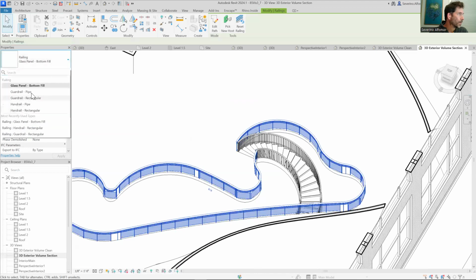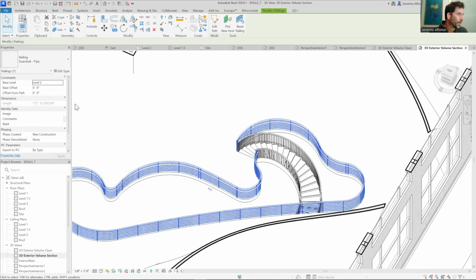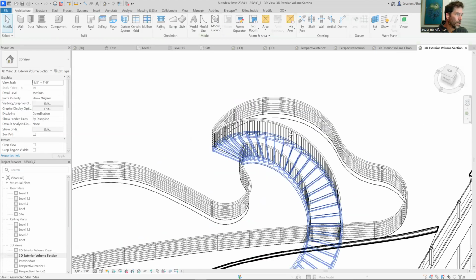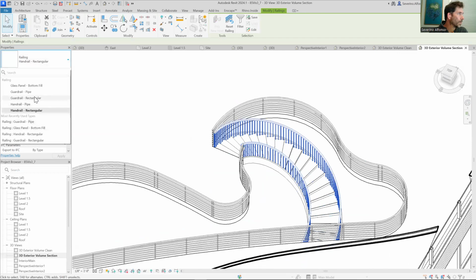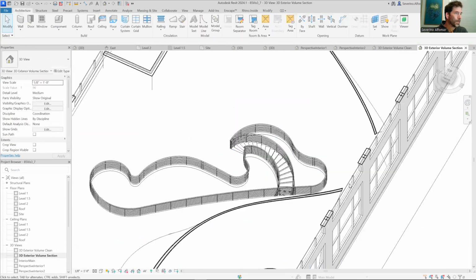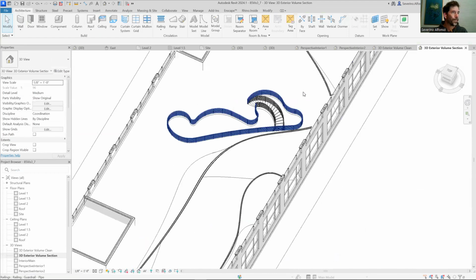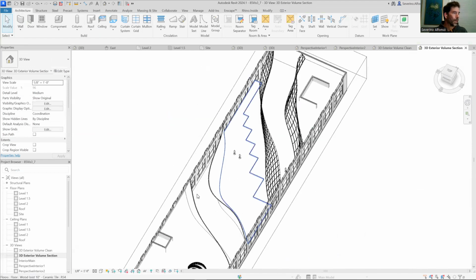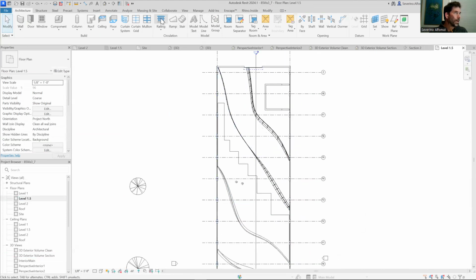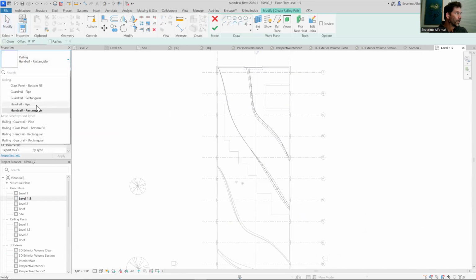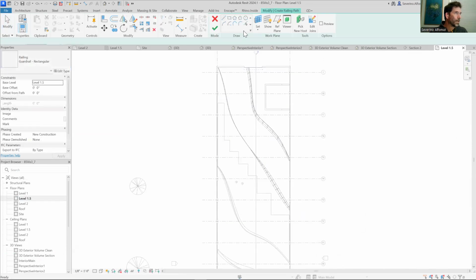Glass, whatever. So order pipe systems. And then you can change the railings of the stairs as well by pressing Control 1 and the other one. So they have similar types. I'm going to use a different railing. There's another one. Going to 1.5. See that. And then I'm going to select railing. I'm going to choose a different type, say rectangular, and also pick 1, 2.